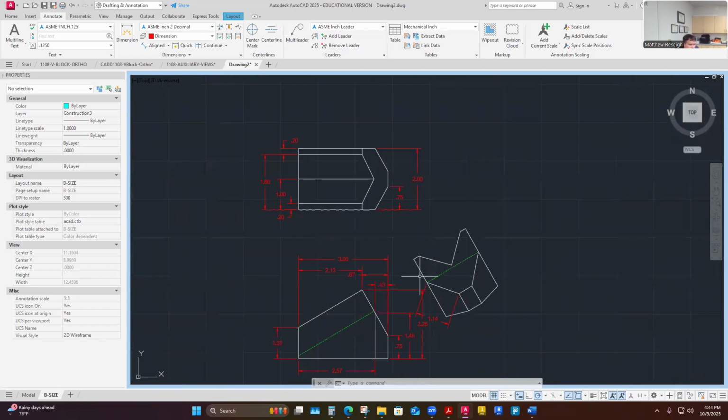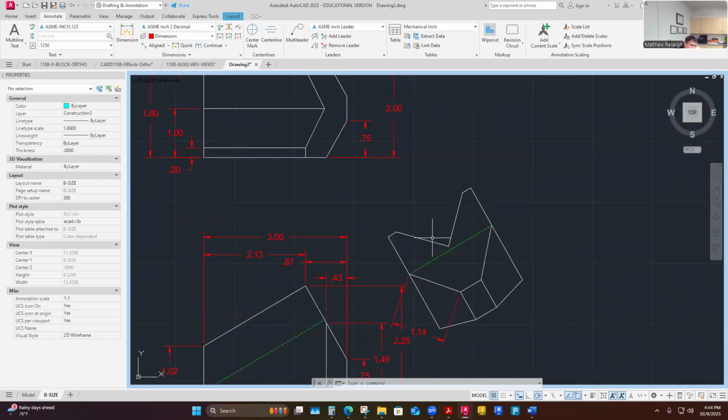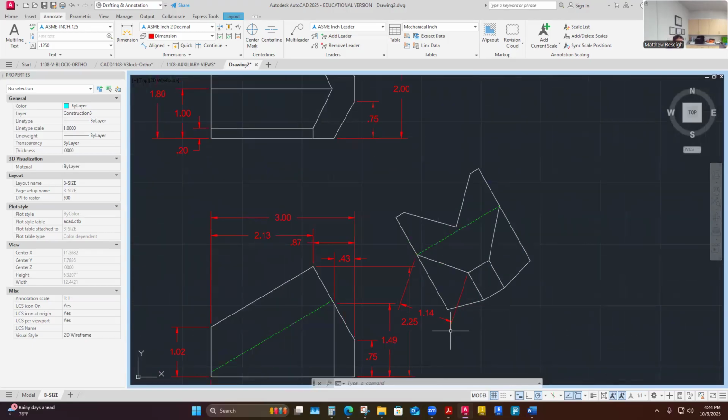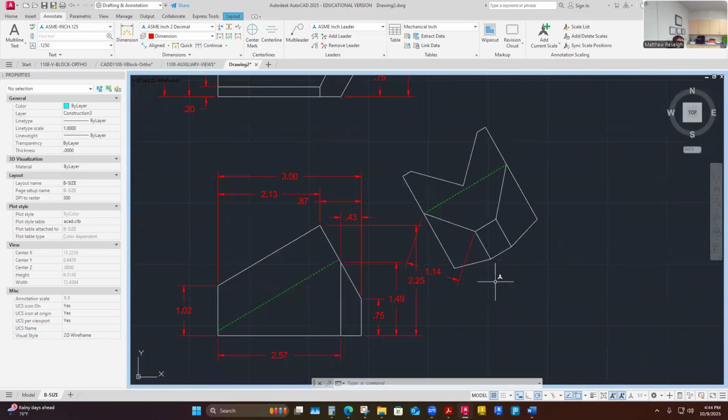It might be better to pull from the bottom up because I do feel like I'm starting to fall into the category now of establishing a fourth control point. In order to get that 0.8 dimension that we use to draw the depth of that, the only place it really shows up as true length is in this auxiliary view. I don't have a bottom to pull from here. My bottom is this point here, but that's my bottom edge.